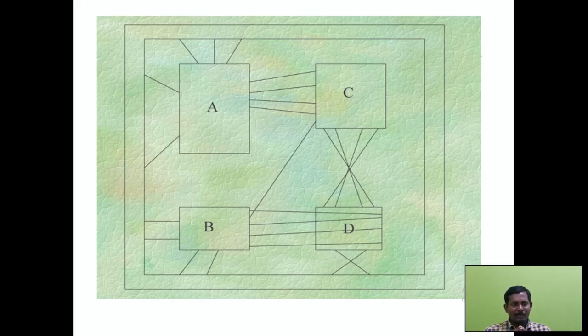So accordingly, to minimize the connectivity, we need to analyze the number of cut sets, which plays a major role in the partition. So during the partition itself, we need to analyze the length of the wire connectivity and the cut set. Cut set means how many lines interconnect between the partitions.